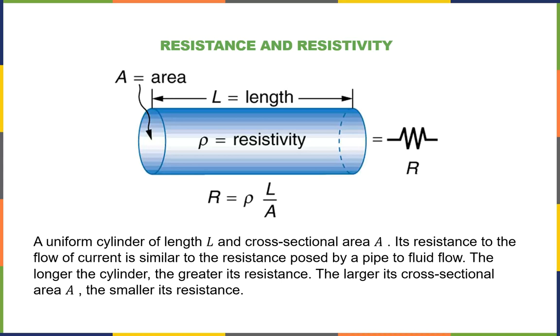The resistance multiplied by that current gives you the voltage drop, which is how much energy you're losing per charge, how much energy is going into heating. So if you're going to have more current flowing, you need less resistance or you're going to start a fire. That's why they have bigger wires. If something doesn't require much current, you can have a very small wire, but if it requires a lot of current, you need a bigger wire so it doesn't get too hot.